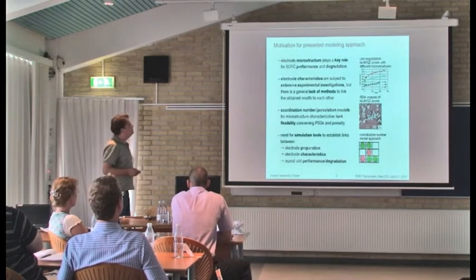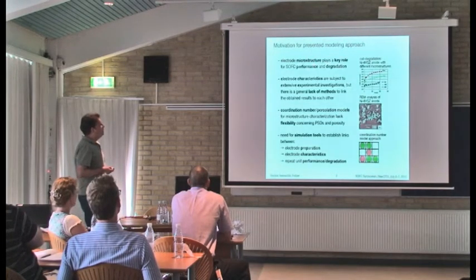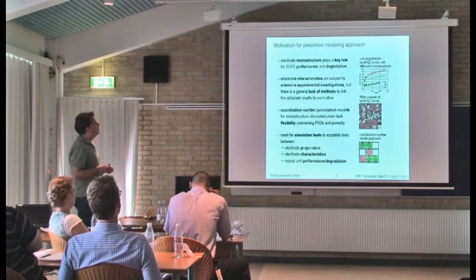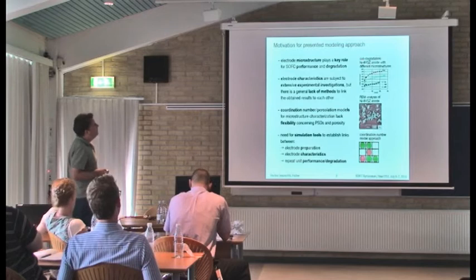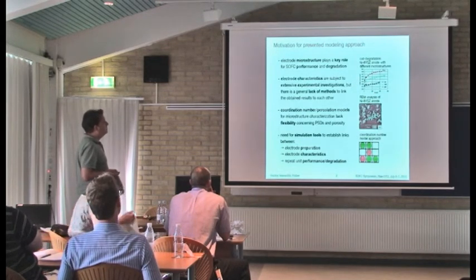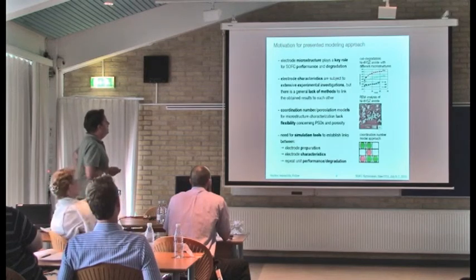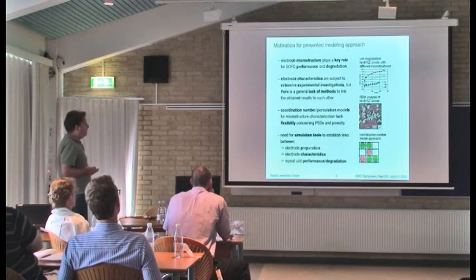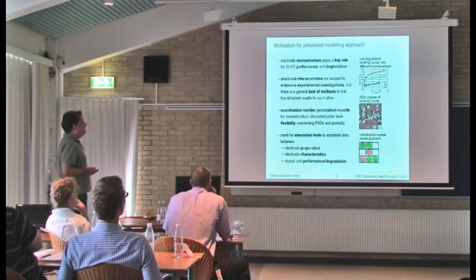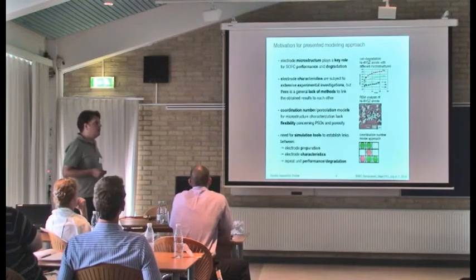So, as a motivation, I think it's obvious to anybody here that the electrode microstructure has a key role both in the performance and in the degradation of SOFCs, which are of course of major concern. As you can see here, experimental data for nickel YSZ anodes, where you have different microstructures, show different electrode resistances right from the beginning, but also different types of degradation behavior. As we also saw today, there are extensive experimental investigations on this microstructure, but I think what is missing are methods to link different experimental data to each other. I think this is the value of modeling.